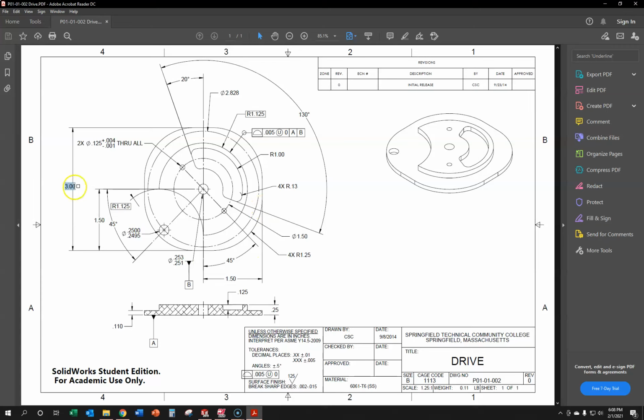And looking at the dimensions here, we have a 2-place decimal. So in reality, we probably could buy a 3-inch by 3-inch square plate. Normally it would be saw cut, so you would have to machine one end of it anyways to get it square. So what I mean by that is you could buy a 3-inch piece of cold rolled steel or something like that. That would probably be in tolerance. You could leave this edge as bought, right?